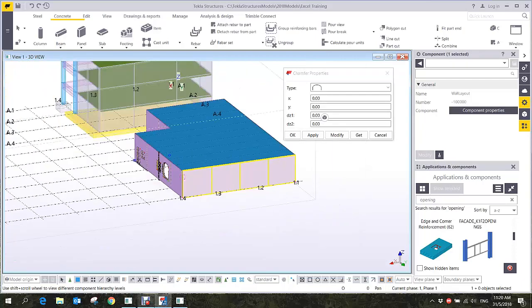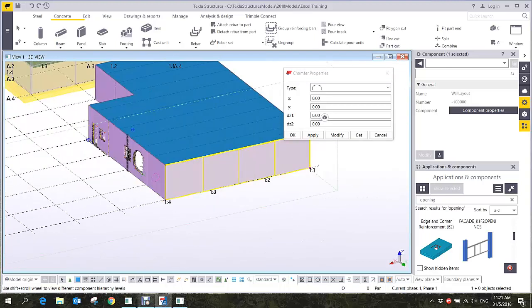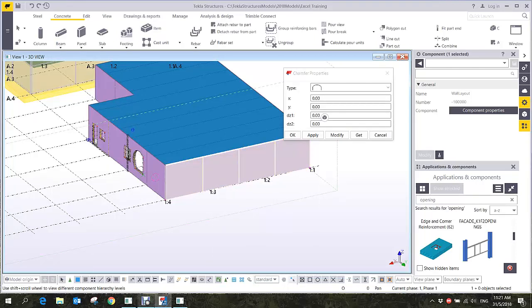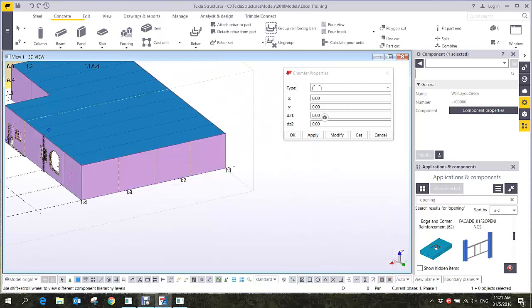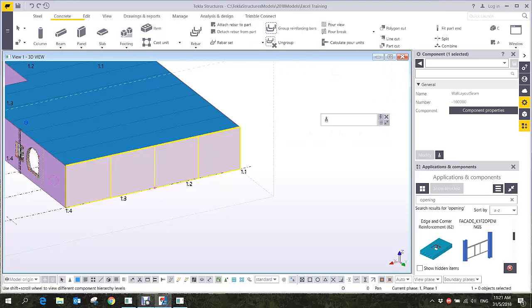Okay, you can try that one. Try it. Go to your wall, select the wall, and then make sure that you select component, select the wall, and then select this direct modification. Once you click the wall, you can see this contextual toolbar.